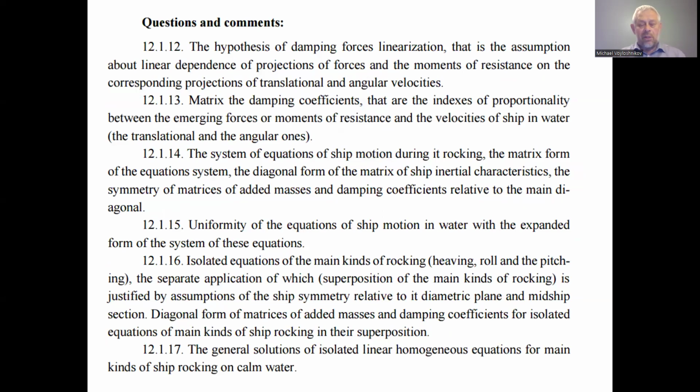12.1.12. The hypothesis of damping forces to linearization, that is the assumption about linear dependence of projection forces and moments of resistance on the corresponding projections of translational and angular velocities. In hydromechanics, it's usual to consider the forces of resistance of water proportional to the velocities in the second power.